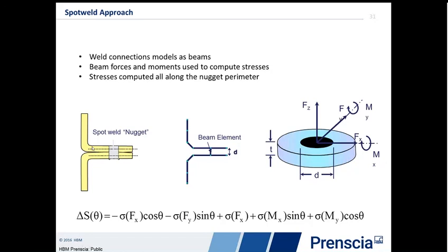And the way that we model this in finite element is we go in and just connect two flanges that have been welded together with a simple beam element. Now, there's other modeling techniques you can use here. We have an area contact method that uses multi-point constraints and solid elements. There are some specialized fasteners, things such as C-weld. There's also a method that uses pentas rather than hexas as an area contact as well. We'll just focus in on the beam model. They're all actually supported though.